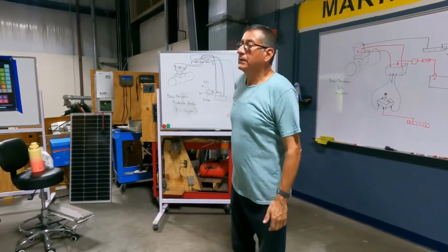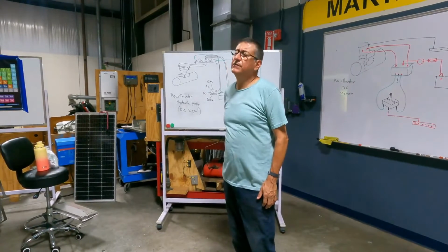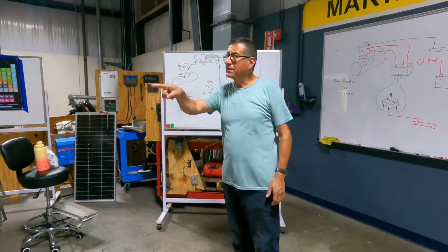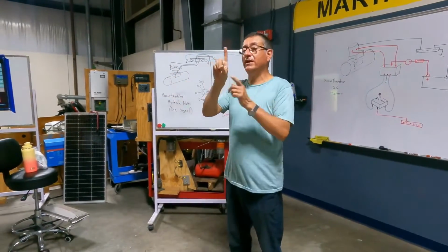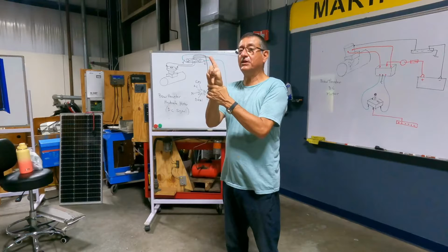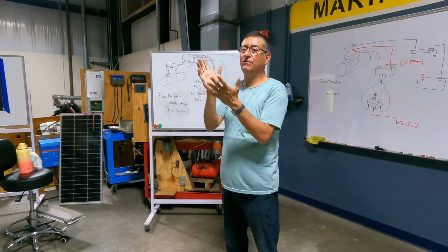Is there a good way to pressure test that? Can you just unhook the line from both sides, cap one of the sides, then throw a valve on it, and then just pressure test it with air? Yes. You pressurize the line at both ends, and you see if the gauge in the pressure tester stays constant. And if the gauge goes down, what happened? You have a leak. Replace that line.